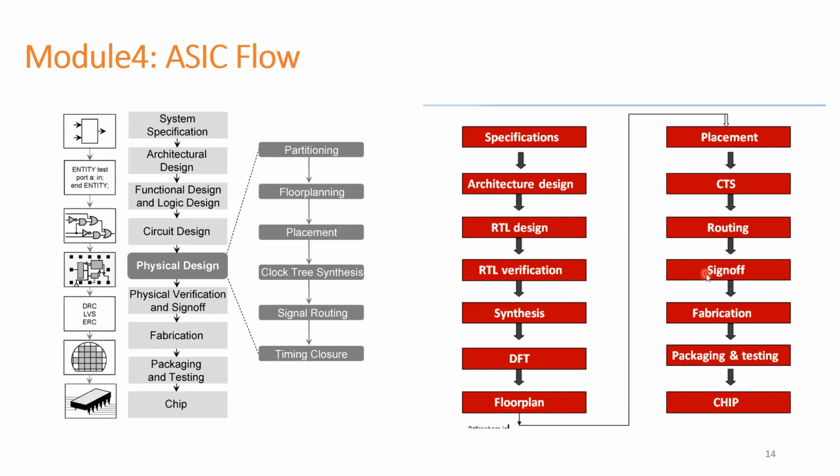Once that is done, we will give the database to physical verification team and IR drop analysis team. What they will do, if there are any design rule violations, the PV team will check for DRCs, LVS, antenna, and DFM checks. They will do all the sign off checks. And the IR drop team, PDN team basically we call it as.